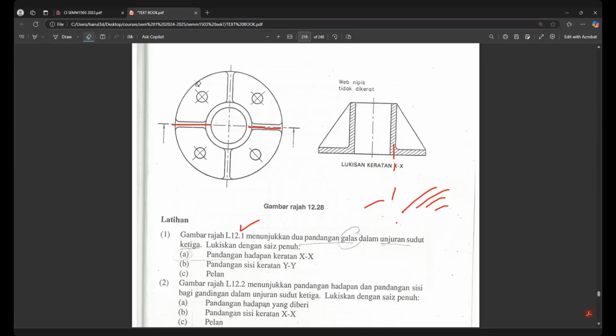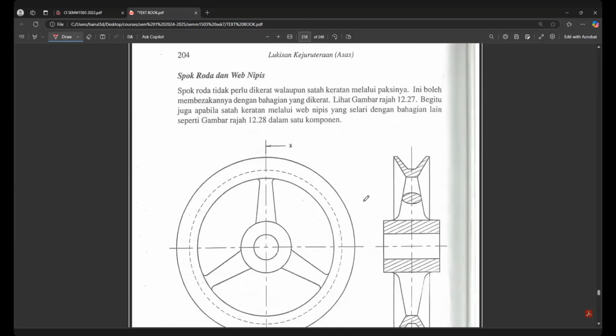That's why they make only the outline of it. They have the outline of this triangle. Only the cylinder and the base are hatched. The rib, can you see the triangle is not hatched. Another thing not to be hatched is a component like this.